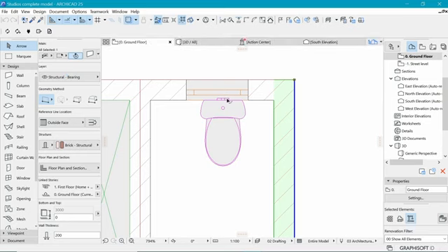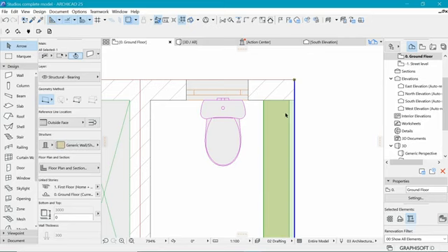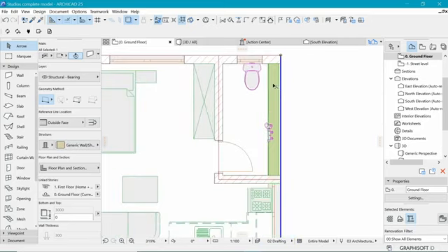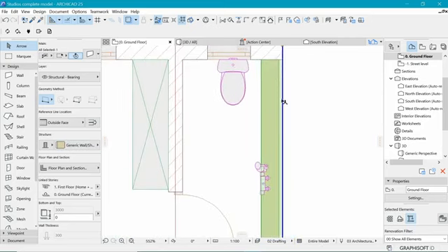Yeah, I prefer that. Okay, so with this selected, you can see that we have different methods that we can draw that wall. So the first one is the simplistic one that we used previously, but then here we have how to make it. We have the second option, which is for making it composite. So if I select that, you can see that the wall has changed to a layer here plus another layer. So we want to make our own custom layer.